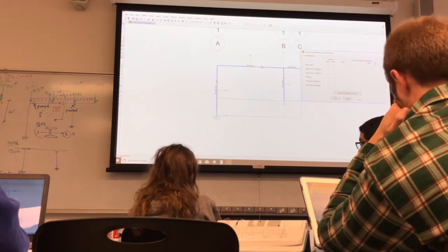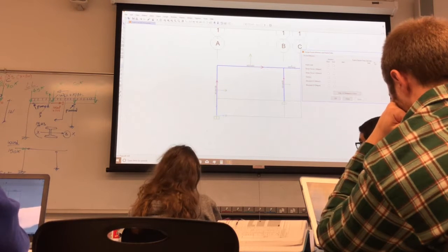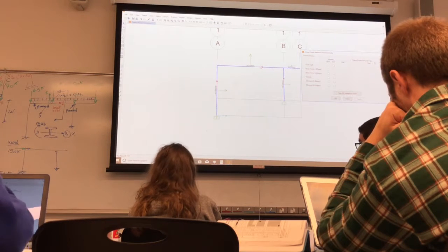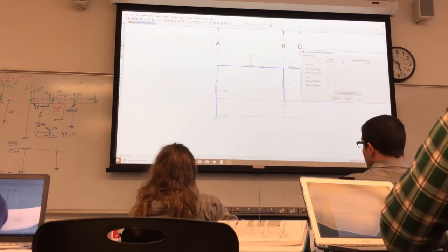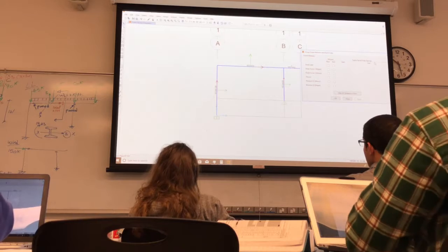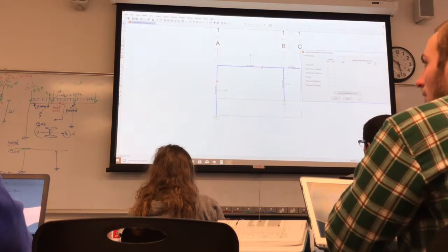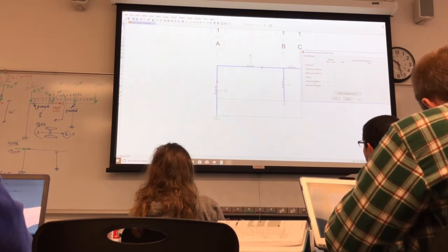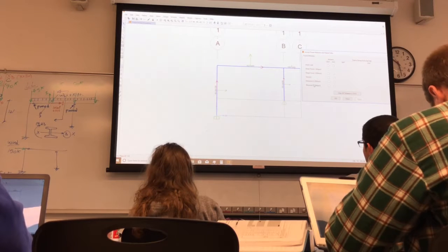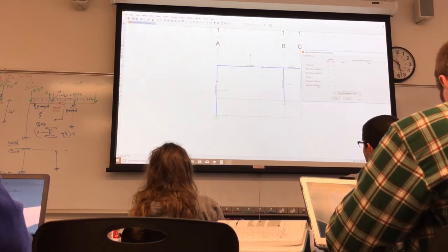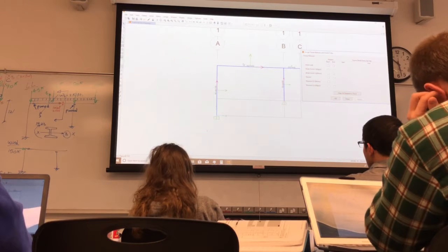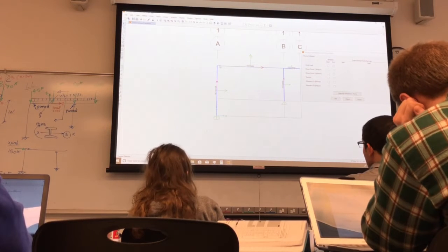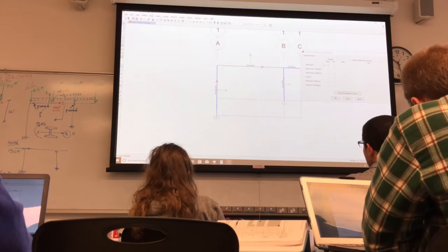So just the axis, 3 is the x-axis. That's the whole idea. Now when we put a pin, that means we don't have a moment. We're releasing the moment. You see there is moment about 2, moment about 3. We're releasing the moment about 3. That's measured axis. Even SAP calls it measured. That's the MX. So for this beam, we want to release the moment at the start node.